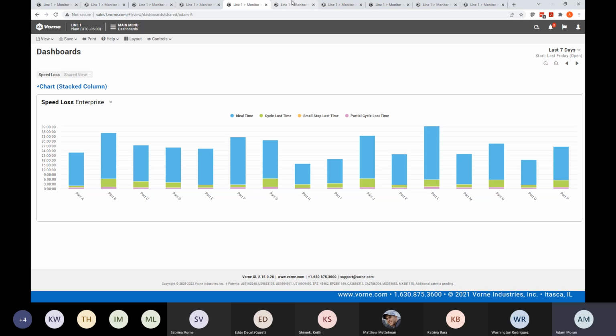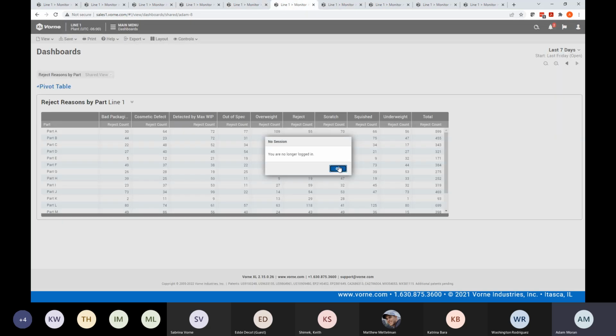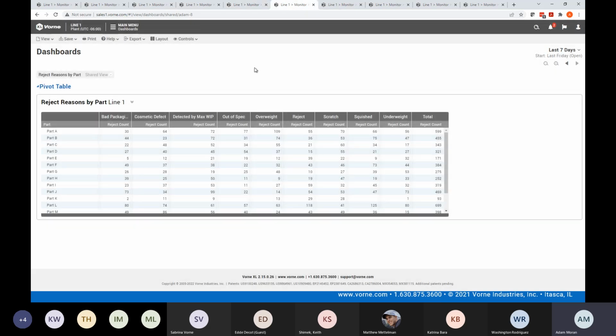We're going to talk about the final component of the raw OEE score, which is OEE quality. Specifically, we're going to be looking at reject by reason code. So one of the things we want to introduce at this point, when we're creating this visualization, is the concept of poka-yoke or mistake proofing. When we look at reasons, we're looking at something that's already occurred. So then when we look at why we're going to be analyzing our rejects, we're going to be looking at two of our underlying themes, which are intent and outcome and contributions to the whole.